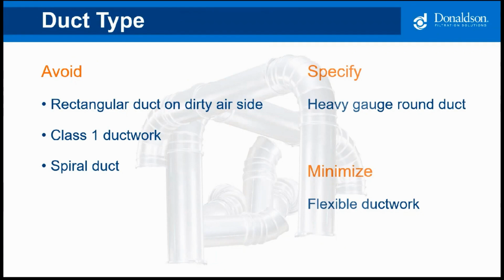Flexible duct is popular because it allows operators to move the hood locations to fit their process. However, that comes at a price because there isn't a smooth inner surface inside the duct. When the air moves through it, it creates a ton of turbulence and therefore requires significantly more energy than traditional hard ducting. So if you're going to use flexible ducting, we recommend minimizing that as much as possible.